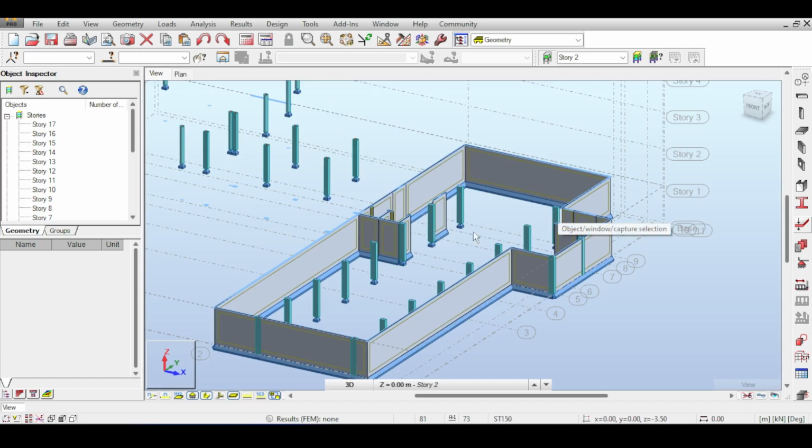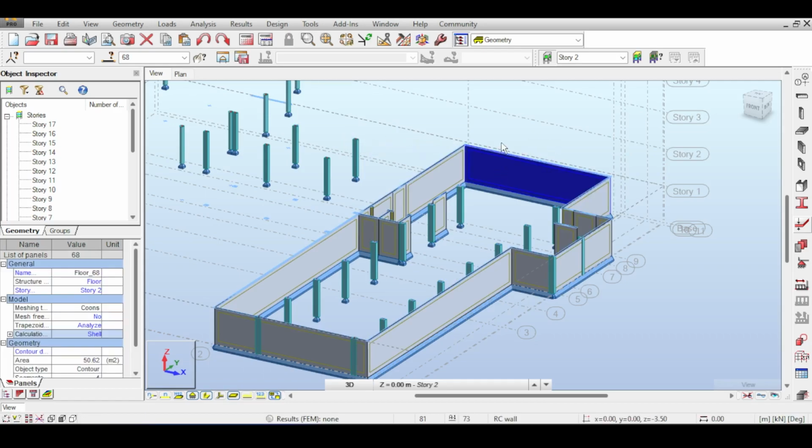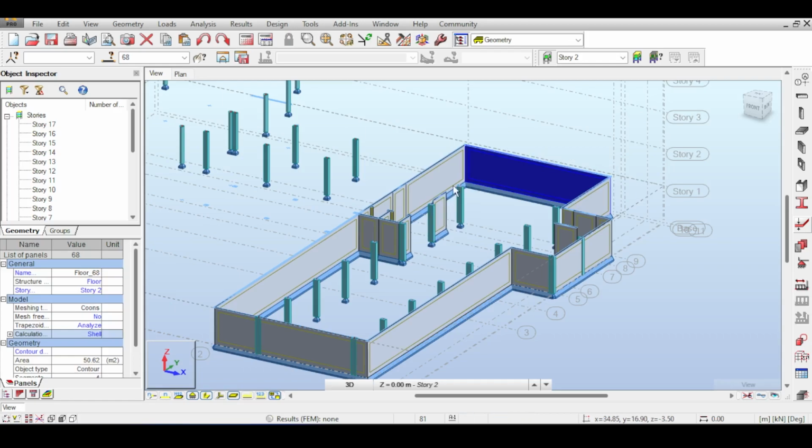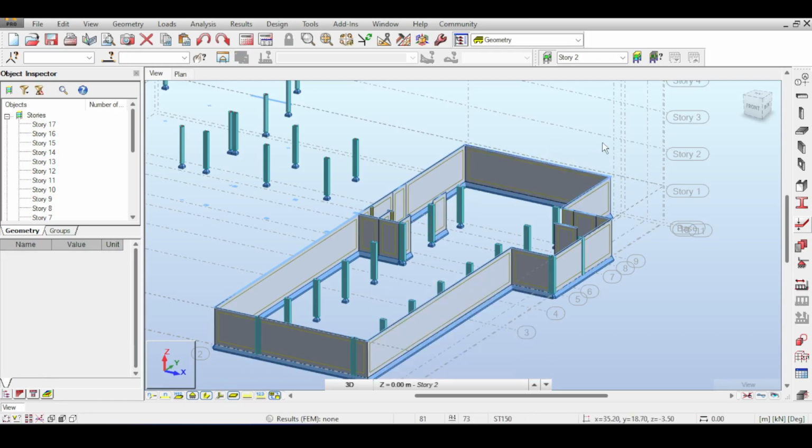So the first question was, why not basement walls? And I want to remind you, maybe I missed saying this in the last video, or maybe I sped up over it. I want to remind myself and you that I'm still thinking about whether to handle a basement wall as a beam or as a column, because each of those has a different reduction of moment of inertia based on the code. And the code doesn't even differentiate. The code calls them beam and column, and there is no limit, like when do I call a beam beam, when do I call a column column.